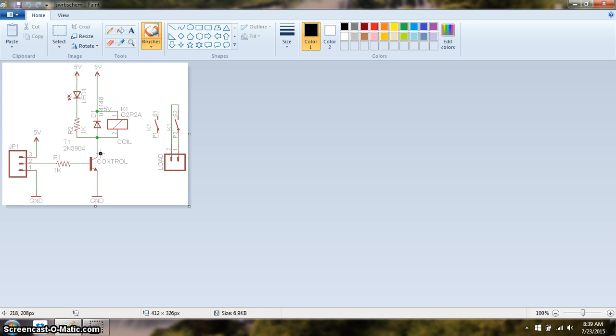Whenever I want. How do I do that? I'm going to do that with this pin. If I provide voltage to this transistor at a certain voltage, I don't know exactly how much, 0.7 volt, I did it a long time back, it's not that important. A microcontroller can provide a 5 volt output. Whenever there is high, meaning max voltage, the transistor will close the circuit. And when you don't have any voltage at this end, by the way, this is coming from this output, it's going to come from a microcontroller.